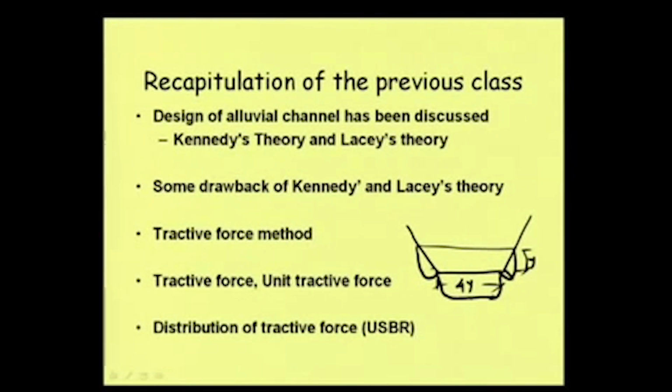So the maximum tractive force we could get at this point. If we compare the maximum tractive force at the bed and at the side, we can see that at the bed it is more, and this can be expressed in terms of W, Y and S. W is the unit weight of water, then Y the depth, then S the bed slope.